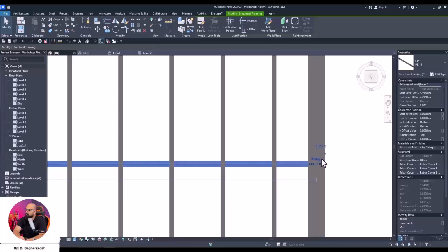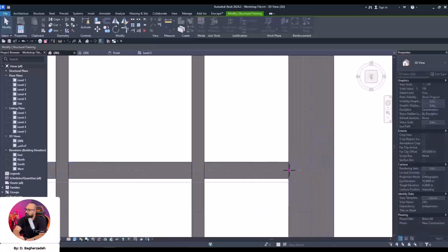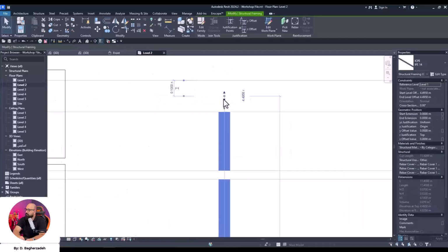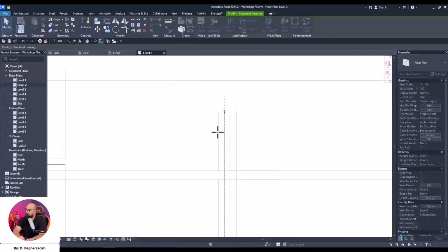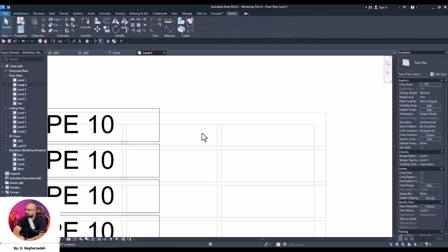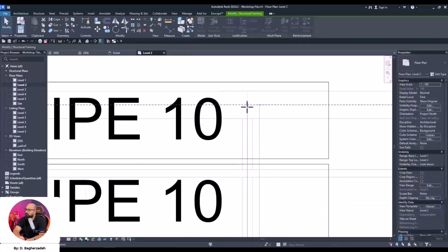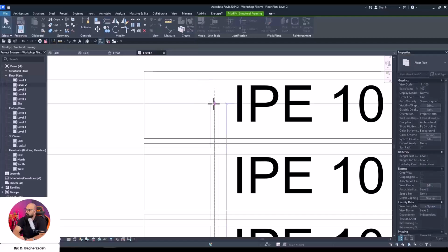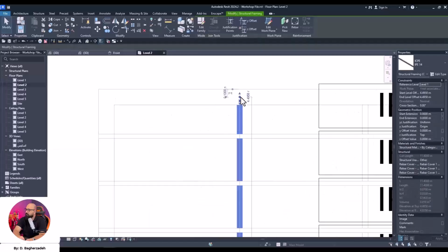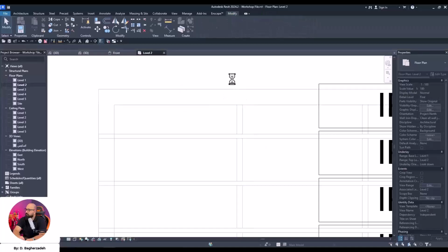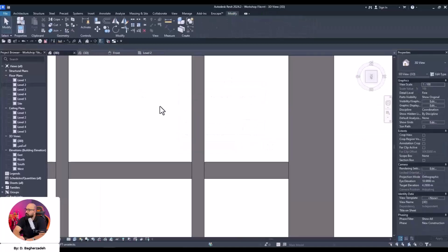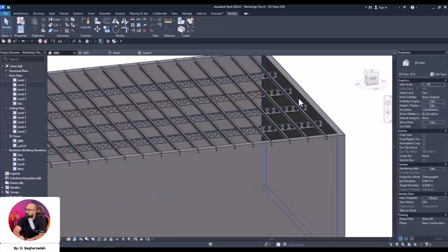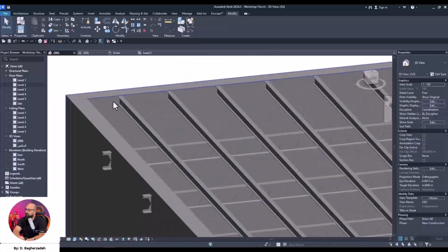And I guess we can even move this a little bit inwards, entering the second level now. Now I'm going to select this and move it right onto the edge of the wall. Right, now we can do the same for the rest of them. By the way, guys, this is something that we should have done before, actually, but this is just an example, so I'm doing it right now. Okay. Right now we have the beams, and we can, for example, use them for setting the rest of the elements that we might need, for example, for the ceiling.